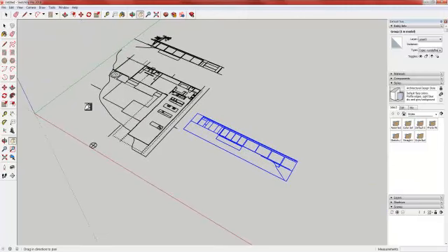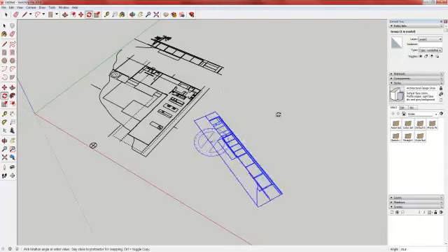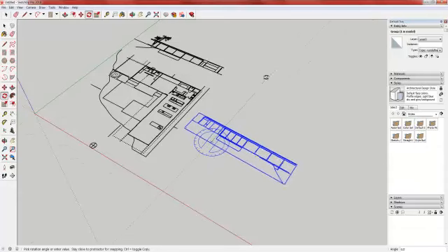The next thing we're going to do is rotate the geometry so that it lines up. Once I've selected my group in my section, I'm going to click the rotate tool, and notice it brings up a little protractor. That protractor allows me to set and change the rotation. I'm going to left click on the geometry somewhere, and it's not too picky where, and then line up with my green axis and left click again. That locks down the base rotation.